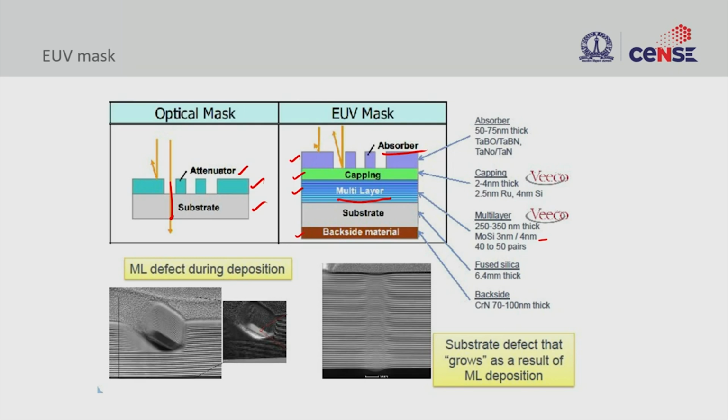In case of any misalignment or non-uniformity, you will transfer that non-uniformity onto your feature. Just to give you an example, a dislocation in the multi-layer stack will quickly result in deformation of your reflection. So substrate defects could directly translate into a reflection effect in this multi-layer deposition.